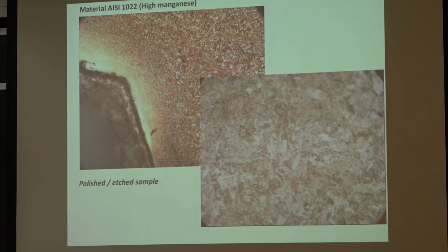So the example of carburizing, and that's the cross-section that I circulated, you can see it at the root of the thread. So the left image essentially is the inside. You have the crest here and you have the root of the thread, and it's square. And you can see that it's a lot darker and a lot finer microstructure here than it is in the core of the part. This is really a cross-section.